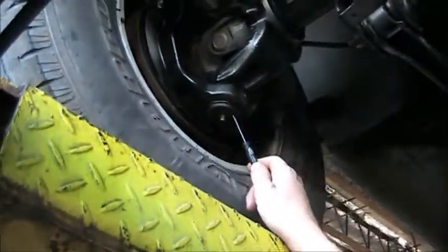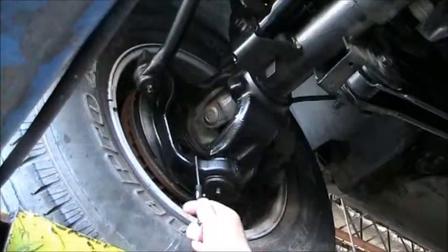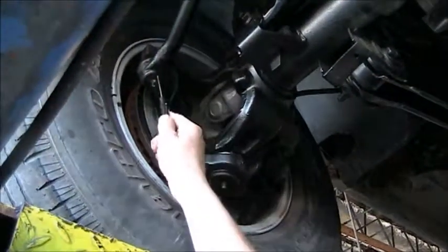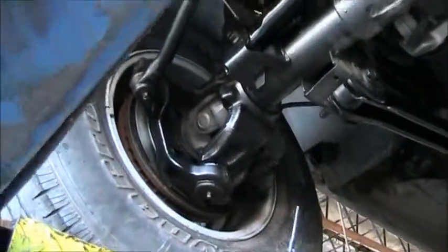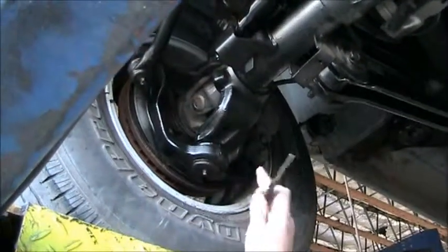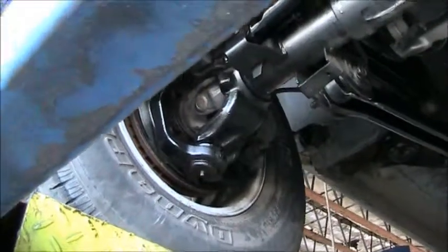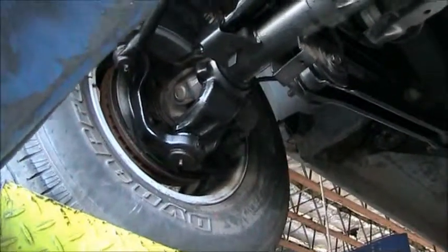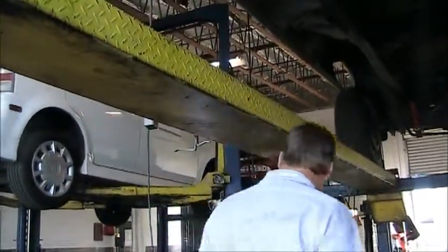On the other side, we have the same thing. We have a ball joint, upper and lower ball joint. They allow the steering knuckle, being this part, to turn. It's connected to a tie rod end, which is connected to the steering box and allows the wheels to turn. Again, another U-joint on this side. That U-joint is to allow the power to flow to the wheels while you're turning still. That completes the basic components of the drivetrain on a 4-wheel drive vehicle.